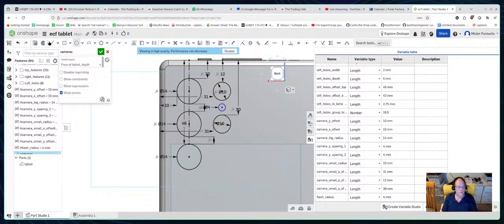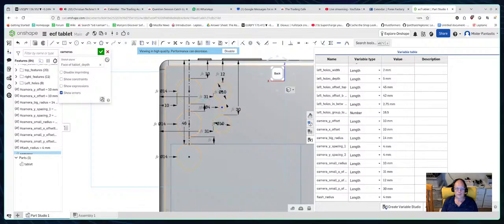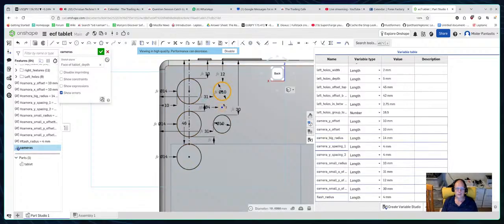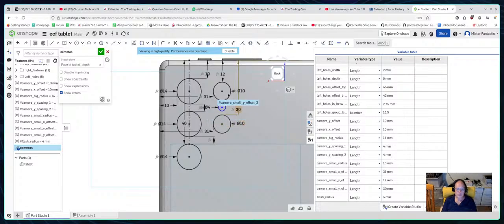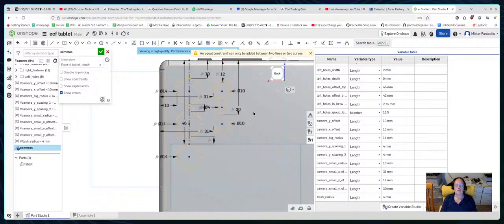And then we need like a... Have we got a constraint about equally spaced? I've got the coincident, concentric, parallel, tangent, horizontal, vertical, perpendicular, equal. So we can go select. Oh wait, I don't want to draw stuff. I want to select. Now you know what I can do is move that out of the way, so I can go select, select, select, equal. Equal only works when we're doing 2 lines or 2 curves.